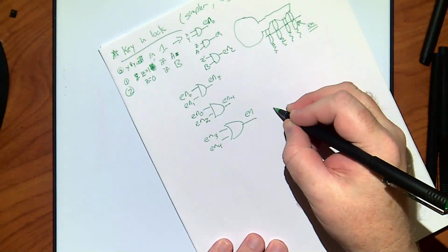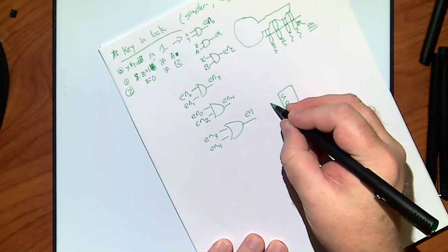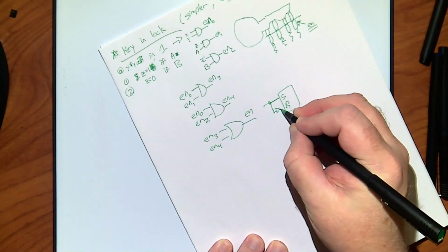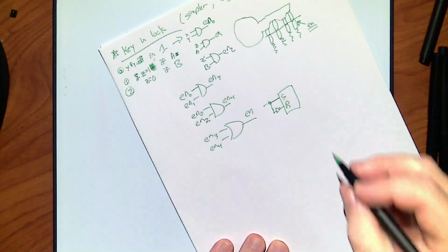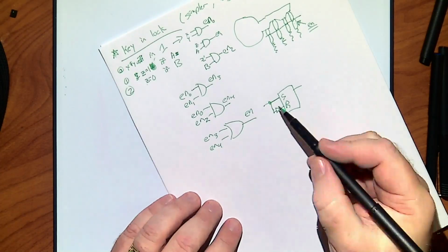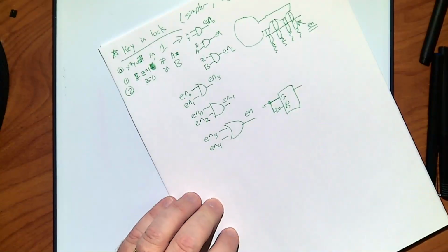I in essence make a D latch. All you do for a D latch, input, invert, and this has become a D latch. From this, we made D flip-flops, this is how you make a D flip-flop. Because if the input here is a 1, S will get a 1, R will get a 0.